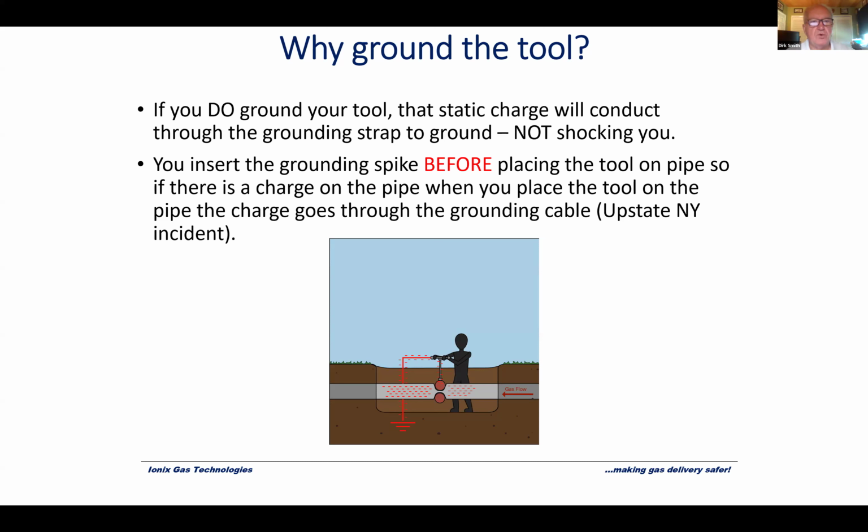If you put your finger in the wall down here in Florida in my office at 120 volts, my finger will conduct 17 amps until that circuit breaker trips, because there's a supply of electrons coming behind it. In the case of static electricity, once that static charge is grounded, there's no continuing generation of electricity to keep up that voltage. So there's a very high voltage, but very low current, and it's over almost instantaneously.